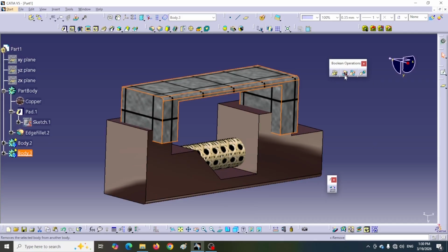To combine the bodies, we use the tools in the Boolean Operation Toolkit. When using Boolean tools, one body is considered the base body. Other bodies are combined with it. If during this combination one of the bodies is part body, it can only be used as the base.